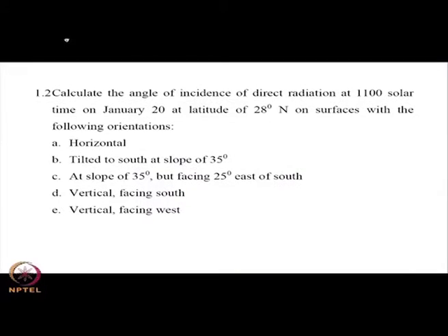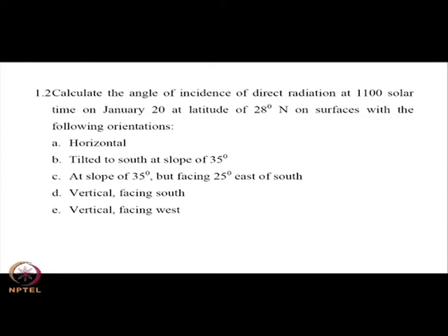Depending upon the time, if it is towards east, 11 o'clock will be better, and if it is towards west, maybe 2 o'clock, 2 p.m. may be better, right. So, this should not come as a surprise, but nevertheless, this is an exercise to learn the orders of magnitude as well as what one can expect qualitatively from a south facing surface, horizontal surface tilted at a particular angle more than the latitude or less than the latitude, which will come a little later.